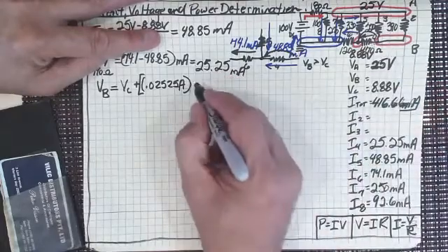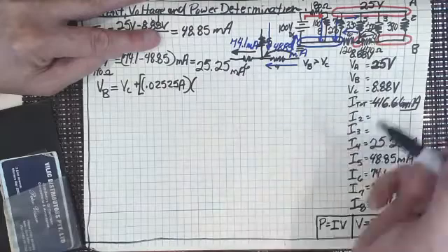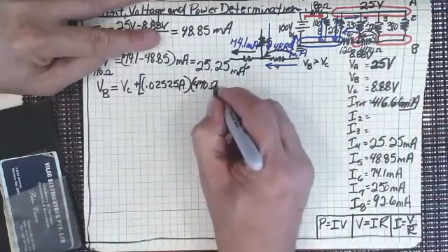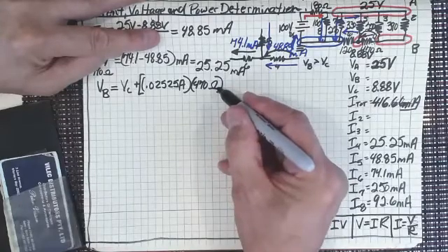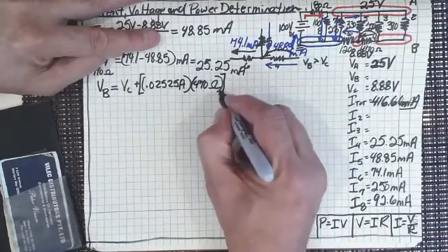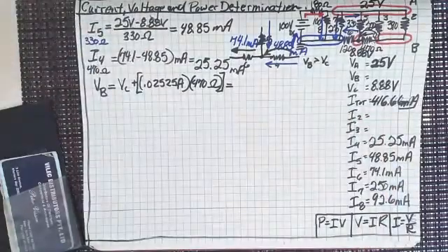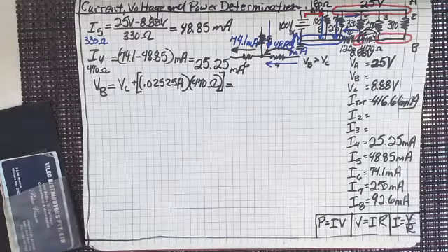And then I want to multiply this by my resistance of 470 ohms. And we know that ohms are already a combination of primary units, so we don't have to worry about that. But we'd have a problem if we were using milliamps, because all of a sudden, where do we put that times 10 to the minus 3 or times 10 to the plus 3 or whatever?